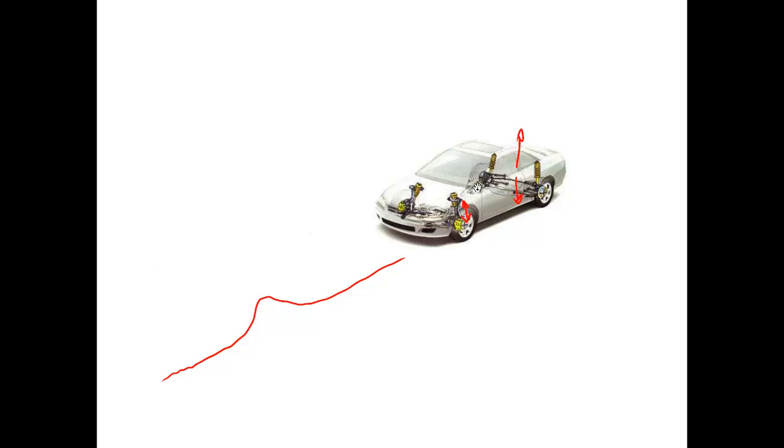These are the shocks in a car, and the incoming signal is, let's say, the height of the road. This is a signal where the independent axis, I guess, is the car is driving at a certain speed, so you can convert it to what will be the height of the road at the time that the tires hit it. That's the incoming signal. And you want the rider's comfort in the car to be good, you want them to have good control, but also comfort. And that's what the shocks are designed to do. They process this incoming signal so that the motion of the car, which is the outgoing signal you can think of, is somehow optimal for comfort.